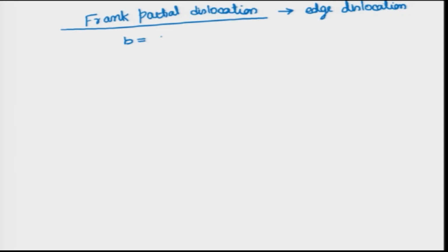These Burgers vectors, if you look carefully, are of the order a/3 <111>, not, remember, the usual partial dislocation that we talked about, which moves away and creates the stacking fault region, that is of the type a/6 <112>. But this is not a/6 <112>. So, this is completely different in magnitude,